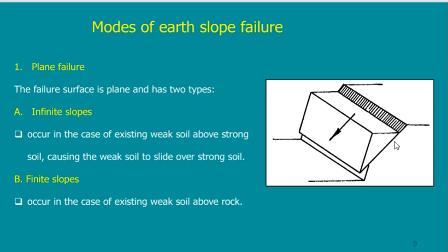The least factor of safety is the critical section where failure might happen first. Usually, if I find a factor of safety of less than 1, it means that it is already a failure. But it is standing just by the will of God. But by calculation, it's a failure.